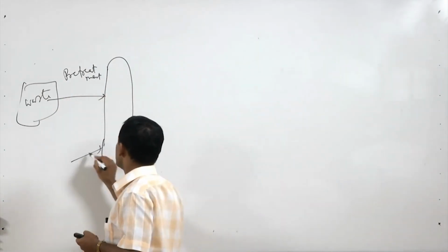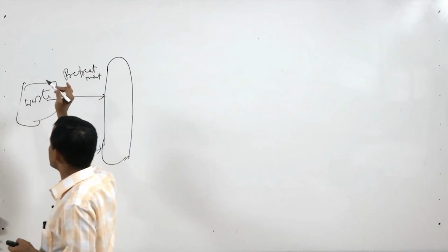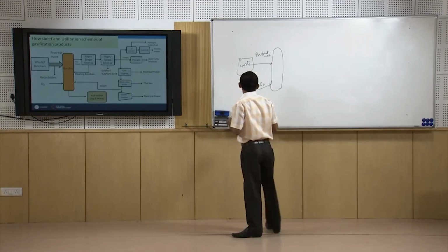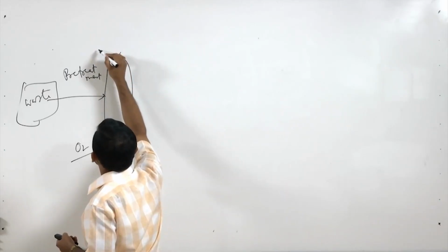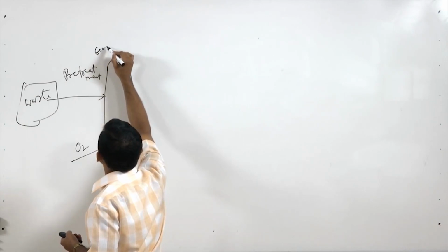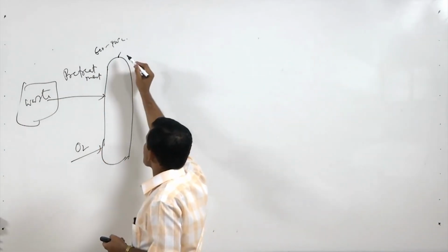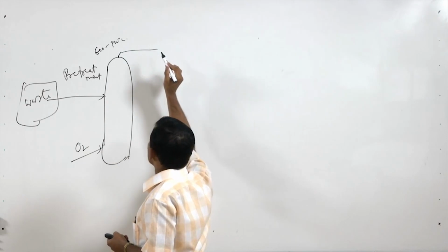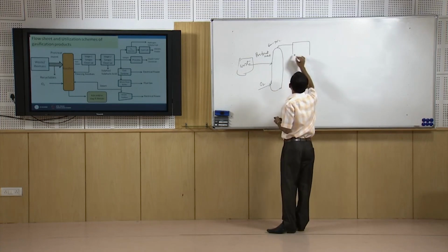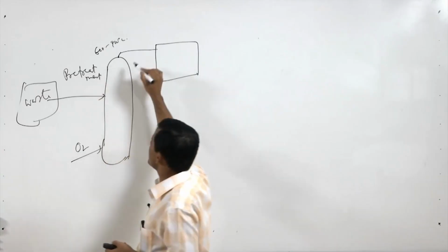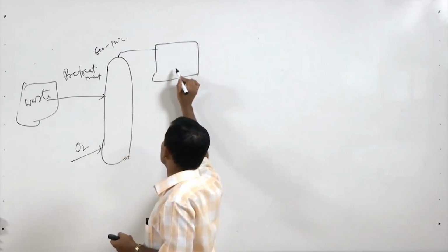The gasifier will be supplied with oxygen or air and steam if required, depending upon the moisture content in this waste. Then it will give us syngas, but here the temperature is high, varying from say 600 to 900 degrees depending upon the type of gasifier we are using. So, that will go out and we need to clean it. Our first step of syngas cleanup is done by using cyclones. The particulates which are carried over are settled down and can be recycled. This is the first step of cleaning.